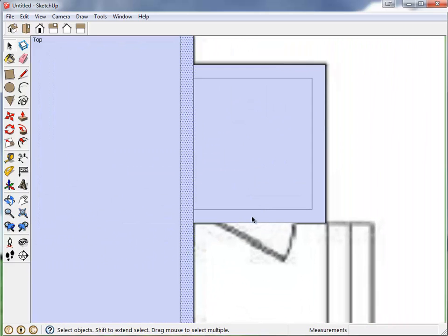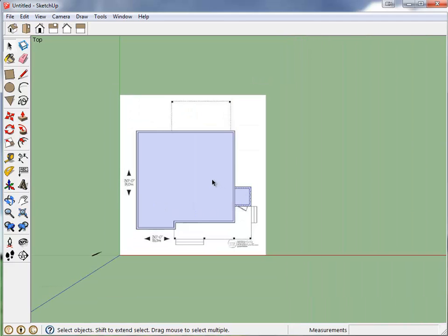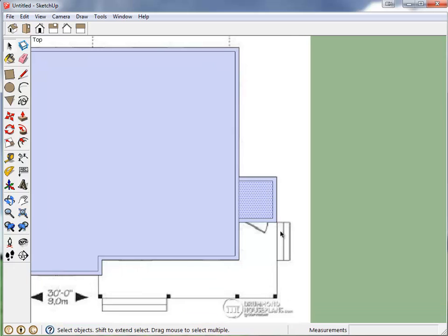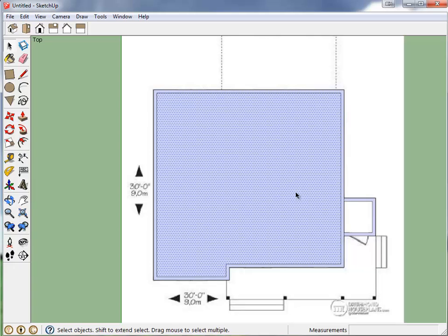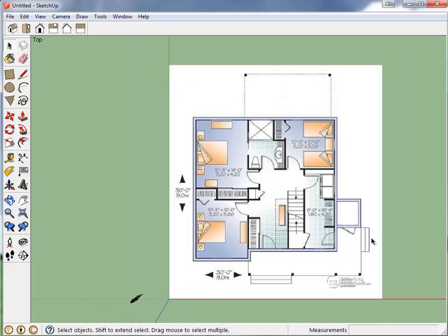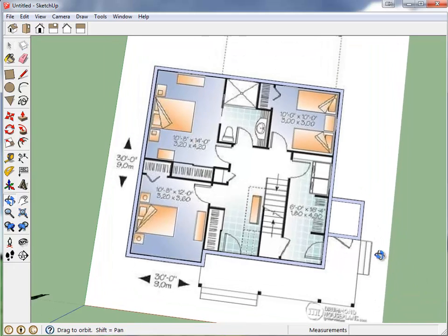This is an important step, so make sure you can click in both spots to get your walls. Once that's verified, click on the inside one time, press delete. We can now see our floor plan with the two separate floors, and we'll spin it around.